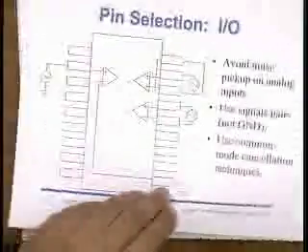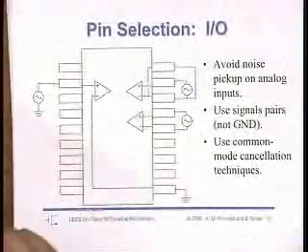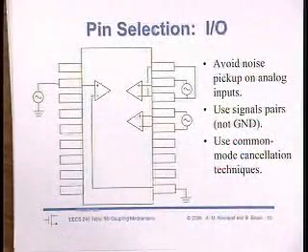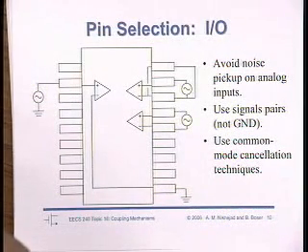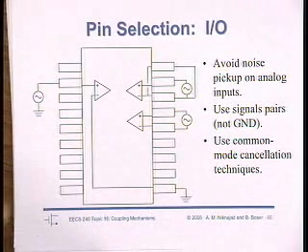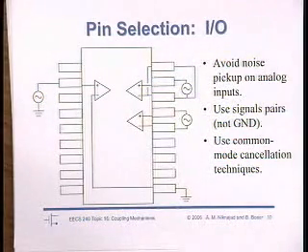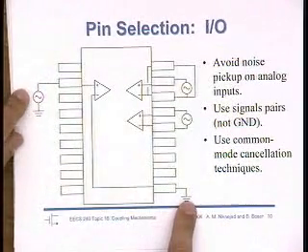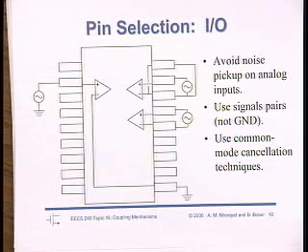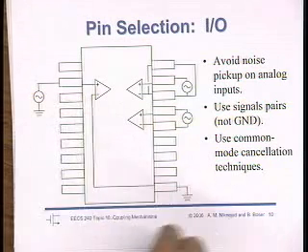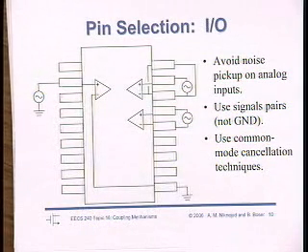Well, not only do we have to be careful about supply, we also have to be careful about our I/O pins. Why is it important to have low inductance on our I/O pins? Say you're designing an amplifier and you find out that you can have even 10 nanohenries of, let's say, source or load inductance, and the circuit still works fine. So is it okay to do something like this? You may cause some interference to other signals, like mutual inductances and stuff. Yeah, it's a reciprocal thing, so not only do you potentially make interference for other circuits, you also pick up interference. So you're designing a good low frequency antenna, a static antenna.